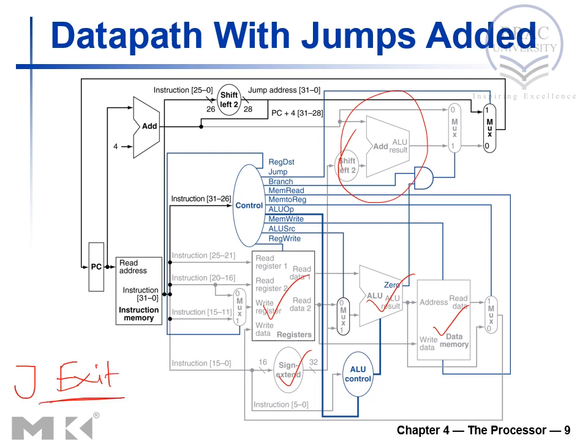So to perform this jump instruction, we do not need a C. In this jump instruction, we do not have any register name or any memory address or anything. We just have 16-bit offset or address. Sorry, 26-bit offset or address. Now we need to make this 26-bit into 32 bits. We shall do it just by concatenation. So we do not need any arithmetic unit, any data memory unit, or any register file.